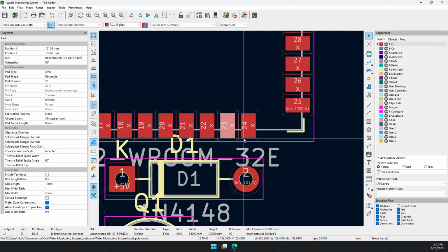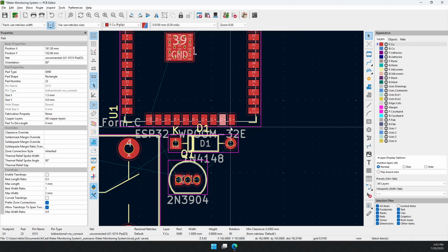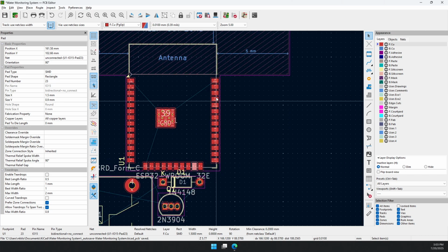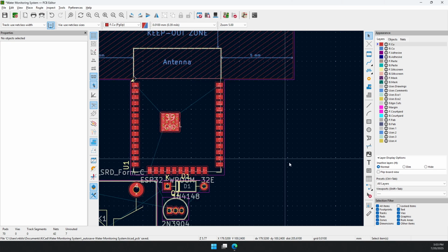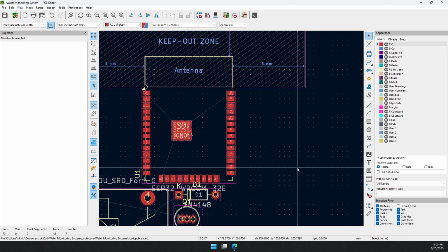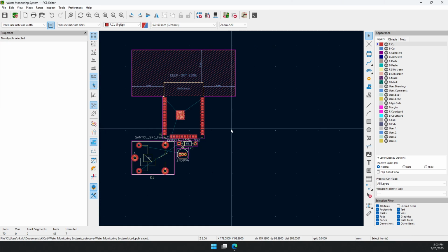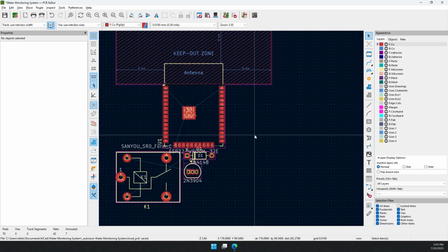Provided that the pin is supported, maybe if I'm looking for analog, I should look for the closest analog pin. If there are none here, I would have to move the diode to maybe this section and use a closer analog pin. All right. So it would all happen in the routing, but for now I'm just going to specify pins. When Lemon is taking on the routing, I think he'll be at liberty to change some of the pins in order to make routing easier. It depends.